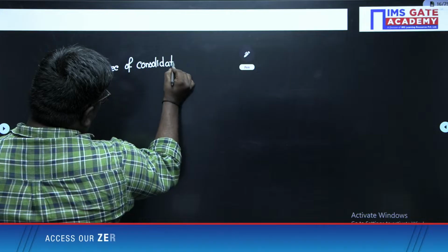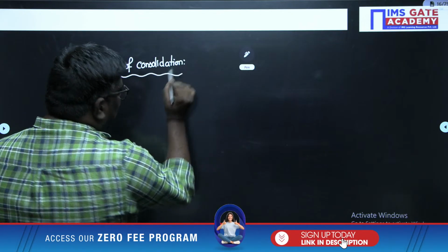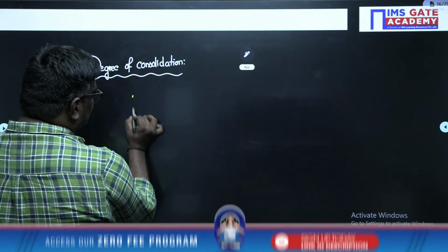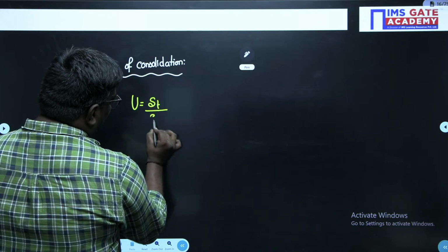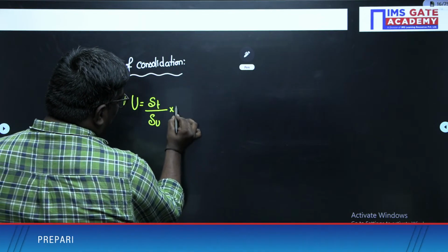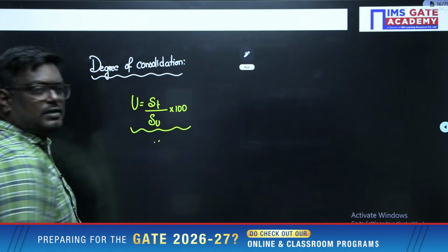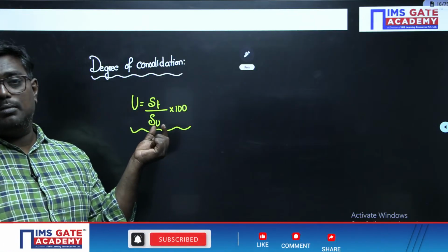Sir, here, my dear students, when they ask you what is degree of consolidation, degree of consolidation is given as U, that is settlement at a time by ultimate settlement into 100. This is degree of consolidation. What's our settlement at a time by ultimate settlement?